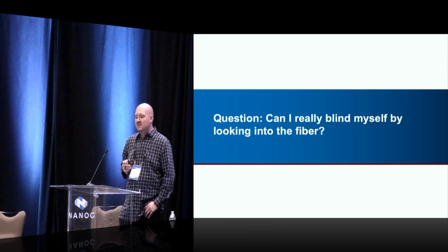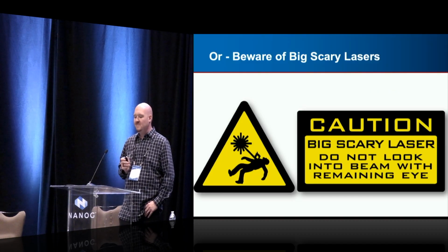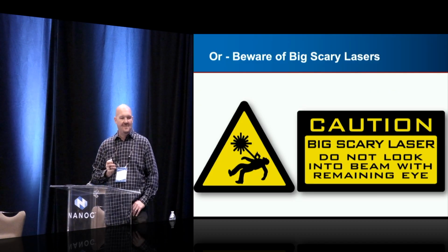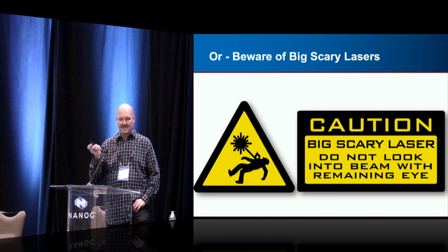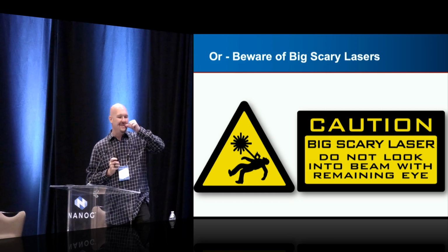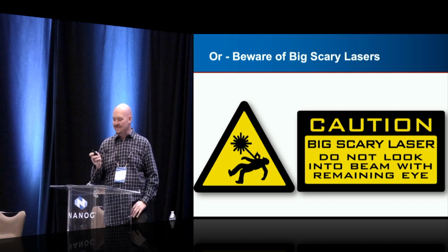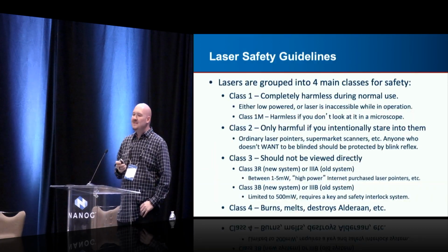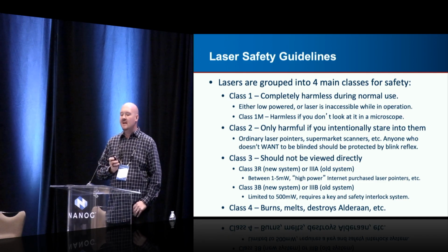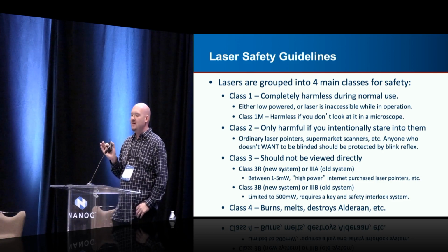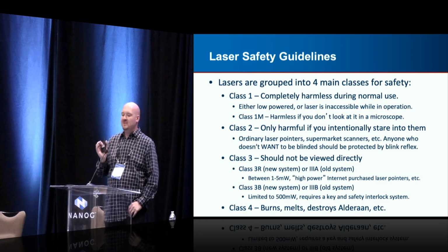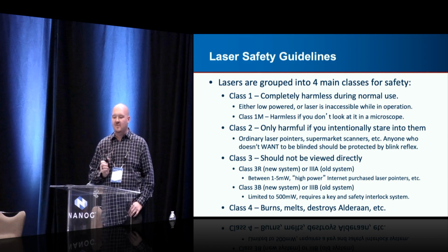People ask me a question, can I really blind myself by looking into the fiber, otherwise known as beware of big scary lasers, do not look into beam with remaining eye. I put these stickers out on patch panels randomly sometimes just to mess with people. It's funny. So laser safety, lasers are grouped into 4 main classes for safety. So class 1 is completely harmless in normal use. It's either so low powered that it could do nothing to you, or it's completely inaccessible during normal operations.